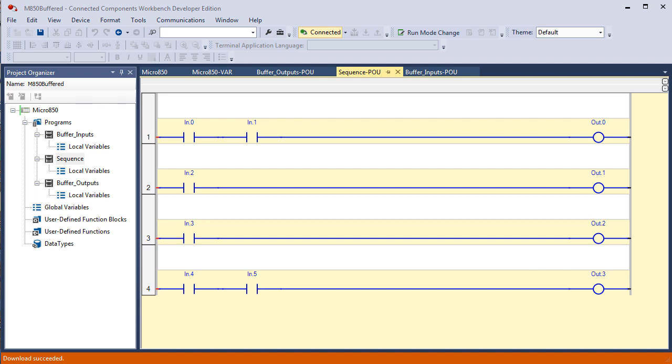Logical statements always start with if, and remember that the syntax of the language is up to the developer. In most cases, instead of saying if in.0 and if in.1, then out.0, else not out.0, they will leave off the second if. In other words, they'll just say if, that would be the rung header right here. If in.0 and in.1, then out.0, else not out.0.